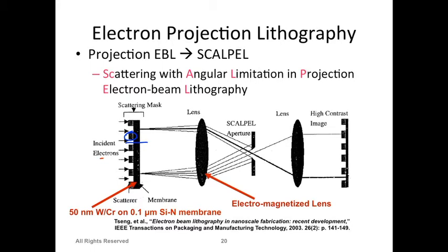Like in one example, what we did was 350 micrometer, right, in a previous class. So we can have maybe that kind of opening, 350 by 350 micrometer, but that would be in silicon nitride, which is on the other side. Then you can tilt your wafer up. Now you have a very thin membrane of silicon nitride, which is 350. Then you can use maybe dry etching, right, to remove it to 100 nanometer. That is what is required in this case.